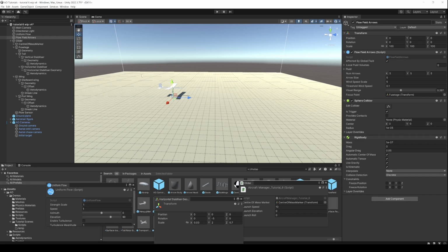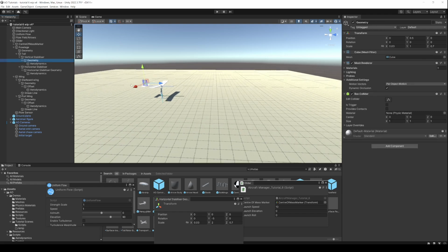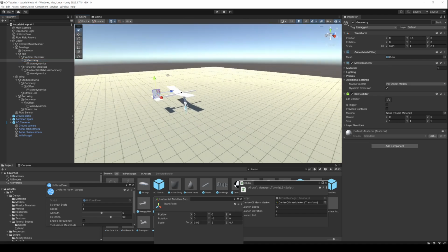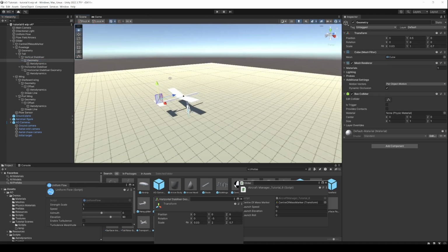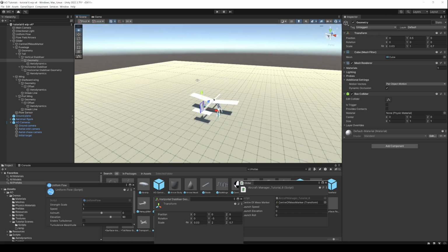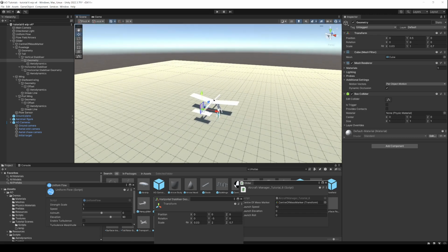So can we get this flying around in circles? And the answer is yes, and we're going to do that by changing the vertical stabilizer. A bit like with the horizontal stabilizer, where we altered the angle to change the aerodynamic balance, what we're going to do here is put a bit of deflection on our fin, so the weather vane, as such, is going to balance flying slightly sideways, and that's going to make our plane turn.